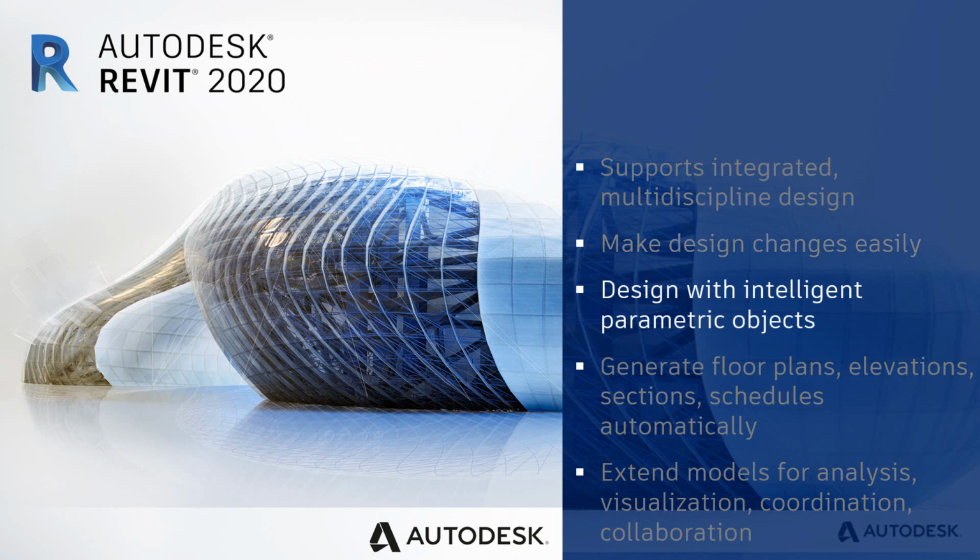intelligently from one drawing to the next, because our drawings are an exact representation of what's in our model. This is important, right? When I change my ducting from a 600 by 600 piece of duct to a 600 by 900, the intelligence that comes with it is that it's parametric, in that the amount of volume inside that ducting changes, which means everything that is generated from that model, i.e. the plans, sections, elevations, and schedules, automatically updates.